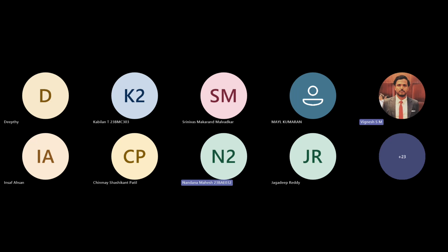Okay, sir, in this moving reference frame method, the propeller and drone are actually attached, but we are keeping them as two separate bodies. Yeah, there need to be 4 MRF bodies and 1 drone, and apart from that, 1 enclosure. There is a need for 5 bodies: 1 body is the drone, 4 different MRF bodies, and 1 complete enclosure. Okay, okay, sir.